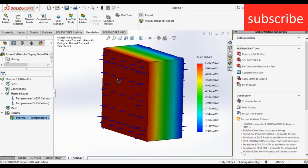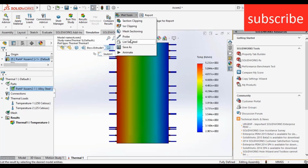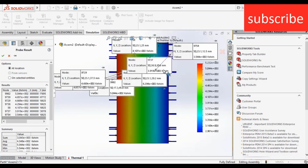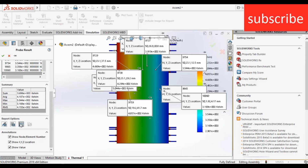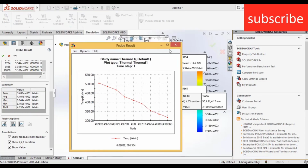Now run this study. As you can see, it plots our heat graph. Now click on this face, press Ctrl+8, click on plot tools, click on probe. Now I am just clicking on points so that I get a rough idea of how the graph is flowing. Remember, it is a 1D plot, so it doesn't matter if I click at the top or at the bottom. It will just be a 1D graph. Okay, I have done a 1D simulation, and click on graph. Here you see the temperature variation. Remember here the units shown are in Kelvin, not in Celsius.